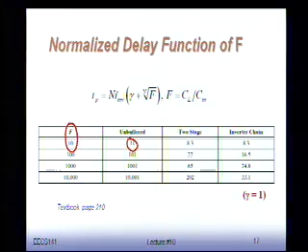If I now put 2 stages in there, turns out that in that case, you figure out exactly how to size your different gates. We see that the delay goes down from 11 to 8.3. So it's smaller. 2 inverters is actually going to be better than a single inverter in this particular case. And actually, if you would find the optimal number of stages, the answer is going to be 2. Not 3. By the way, you always have to have an integer number of inverters. Sometimes you might end up with 3.7 or something like that. Then you have to round it upwards or round it to somewhere a closer integer number. I cannot have half inverters or quarter inverters, unfortunately.